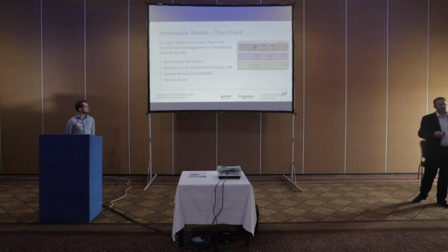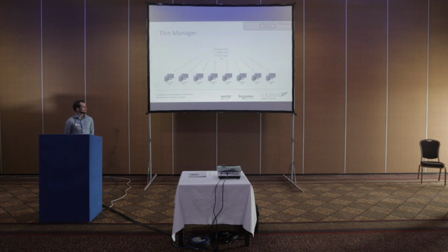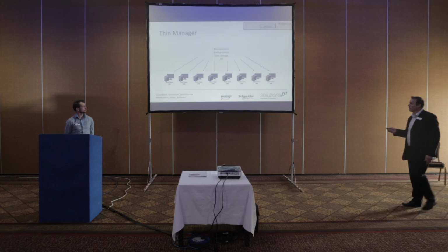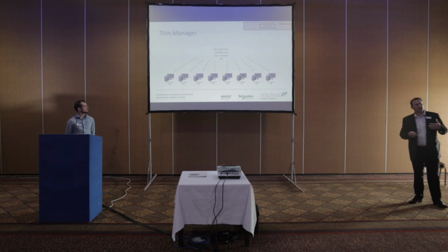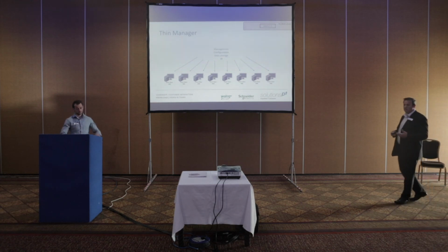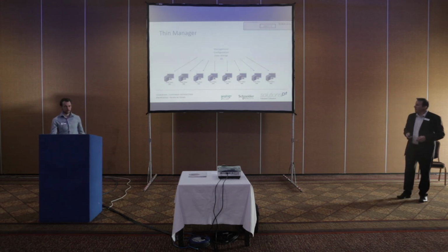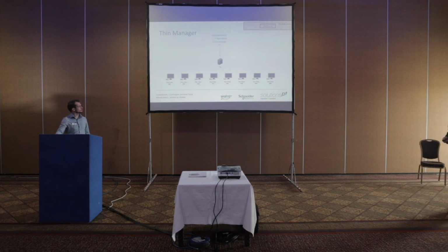And you still want to put in that authentication with Active Directory so that you can secure your access from user to terminal. If we look at this basic example, we have essentially eight thick clients. These are PCs running an operating system that have the SCADA software installed on them. It's easy to see that each one of these is going to have to be maintained, from a patching perspective and updates from the SCADA system. And again, how are we going to improve our efficiency if we have to maintain all 8 of those?